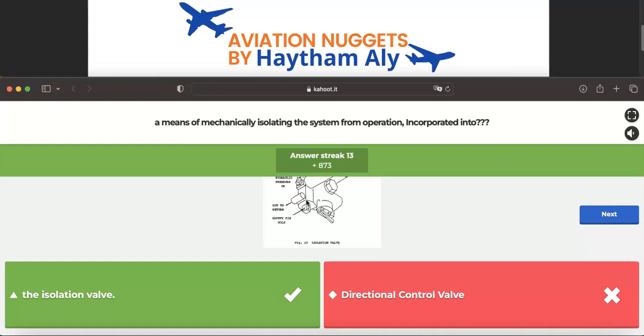And also if they need to deactivate the thrust reverser for flight, they will do hydraulic deactivation from the hydraulic control unit. They will close the hydraulic supply by the lever on the hydraulic control unit that will manually close the isolation valve.